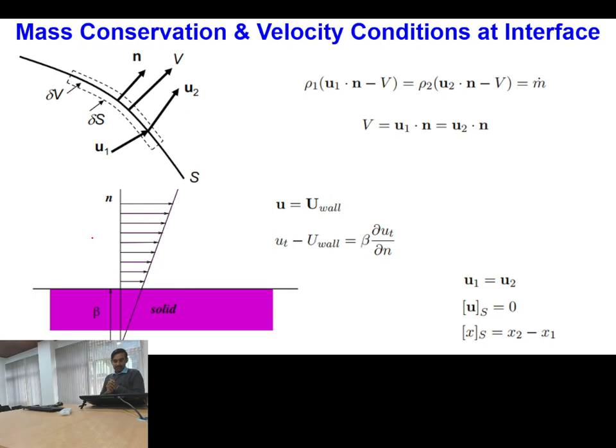Now comes an important point. When we are at the interface, a little bit of idea I have already given you. Again I will quickly go through this, because while we were talking about the kinematic and dynamic boundary conditions, I gave you some idea then also. But what the relation is over here, that I want to emphasize. I told you in the previous discussion that we can model multi-phase flows using two different approaches. One is the two fluid approach and the second is the one fluid formulation.